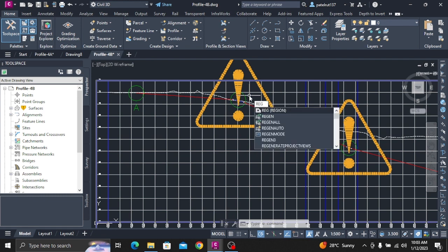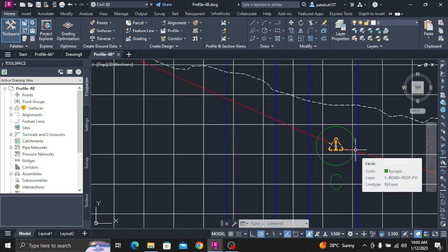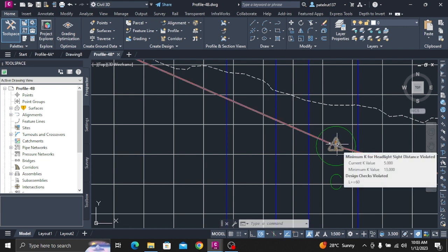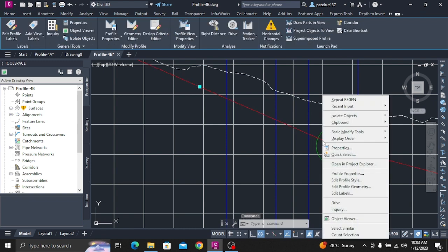In Toolspace, on the Prospector tab, expand the Alignments Road, North-South Profile Views collection. Open Profile 5a.dwg, which is located in the Tutorials Drawings folder. Click the grid to select Profile View PV, 1. Right-click. Click Profile View Properties. Click the Information tab. In the Object Style field, change the Profile View style to Major Grids. Click Apply. Notice that this style change affects the X-axis annotation as well as the grid.